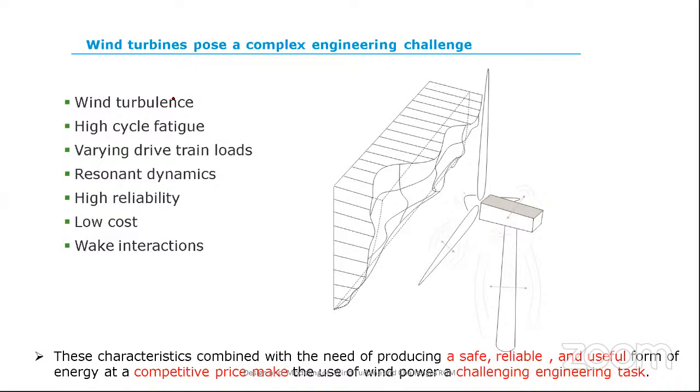When you want to design the wind turbine, the first thing is that it should be safe, reliable, and competitively priced. These are the major challenges of engineering work. Also, the turbine has to be designed for high turbulence, because I told you that the wind has natural turbulence. It has to work with the turbulent nature of the wind and high cycle fatigue.